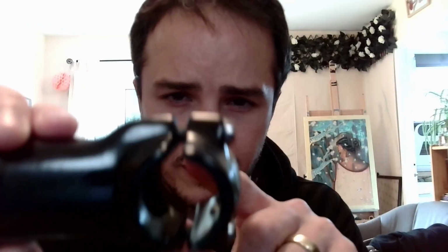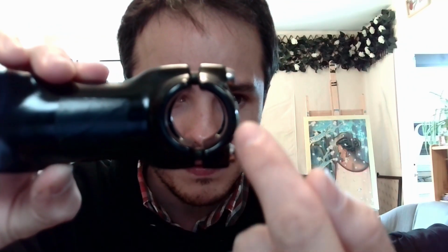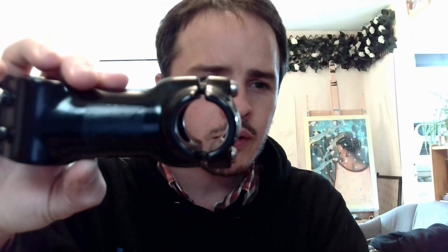Good stuff. Okay, so next, what we want to do is make the barrel shape that this captures. Now, it will be very hard pressed to make that shape on this plane. So what we're going to do is use that sketch to position a vertical plane, and then we're going to do a cross section of the barrel. Maybe the sketch wasn't the best way to do it, but that's okay.